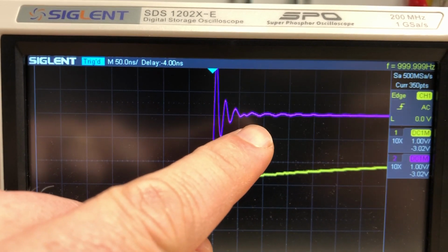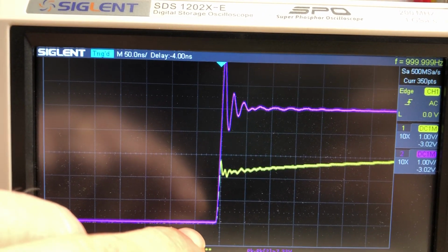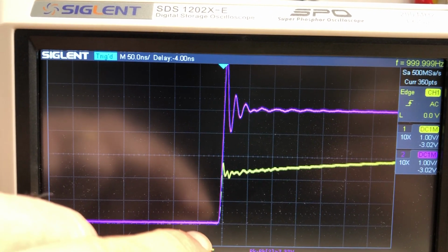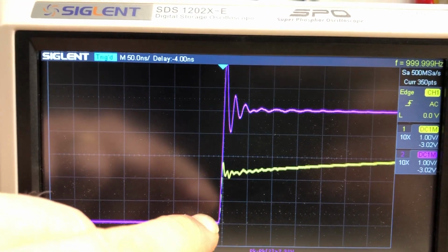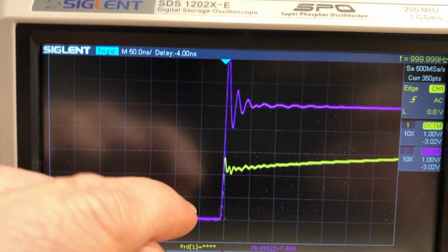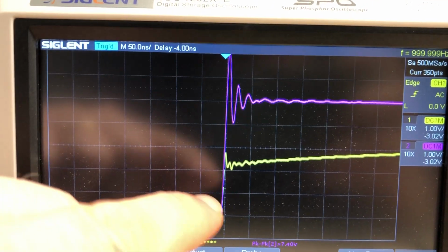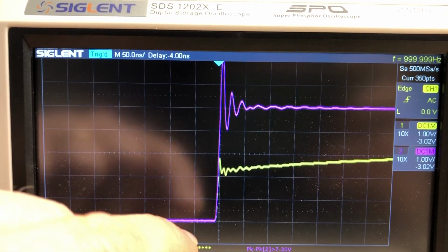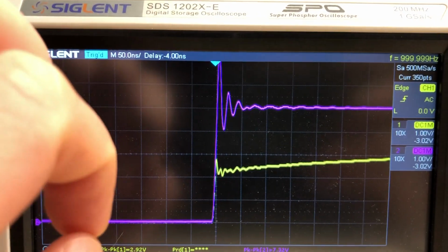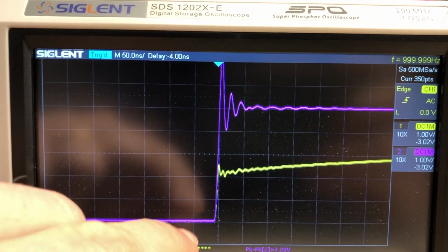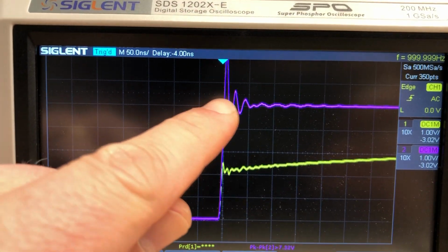You can't actually do that. It's like accelerating to the speed of light. You can't literally go instantaneously from 0 volts to 5 volts. The only way to do that is with this whole spectrum of high frequency components, and you can always zoom in enough to see them.